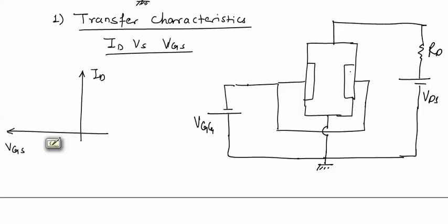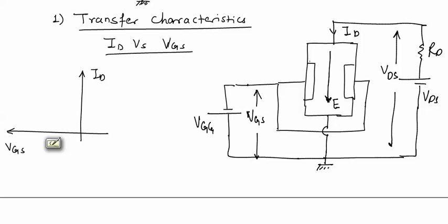Now if voltage VDS is applied to the JFET, the field will be set up in the channel, and due to this field, charge carriers will start flowing and drain current ID will flow in the device. If VGS equal to 0 volt, this voltage between gate to source, the depletion layer width will be somewhat like this. It will be more towards drain end and less towards source end.